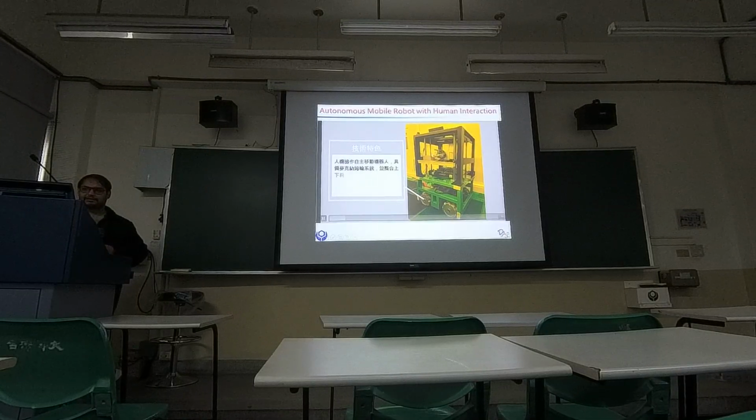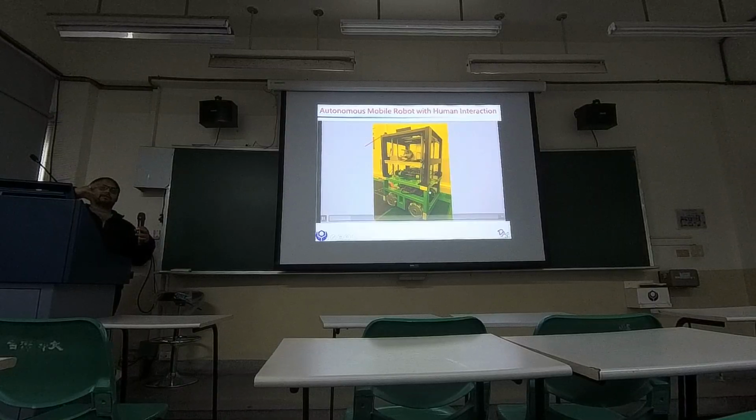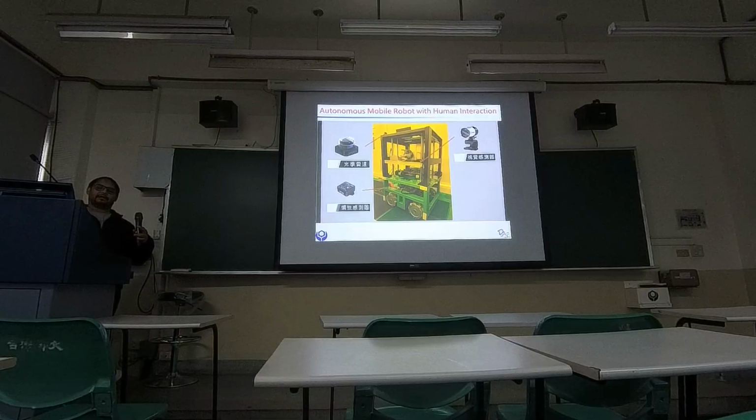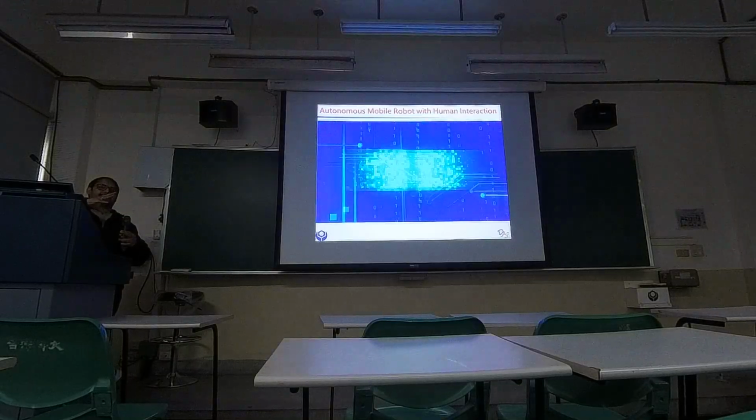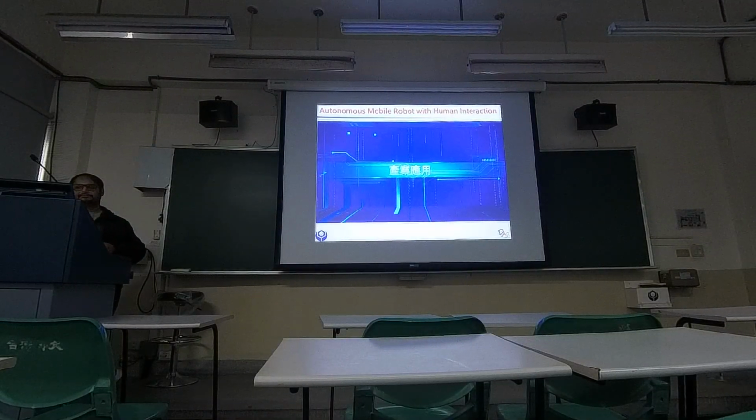We have placed a gripper here because we cannot pick the rolls from outside. These are very sensitive fiber circuit board layers. It is hollow from inside, so everything has to be picked from inside. So we made a gripper which grips in the outward direction to hold it.